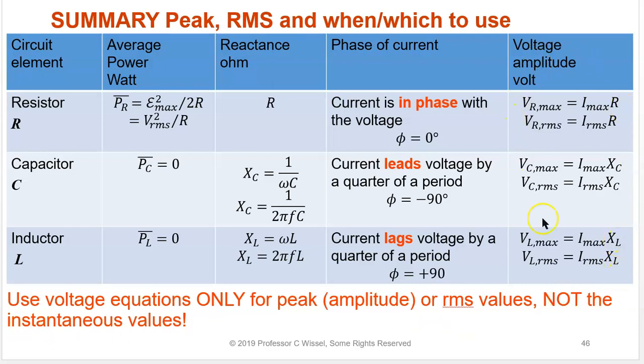Now, be careful with these right here. Use the voltage equations only for the amplitude or peak values or for the RMS values. Do not use these for the instantaneous ones. They won't hold for instantaneous.